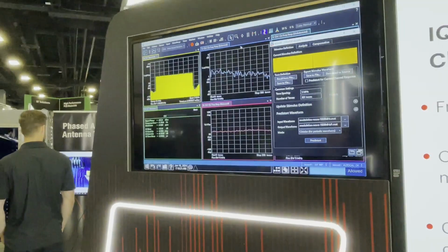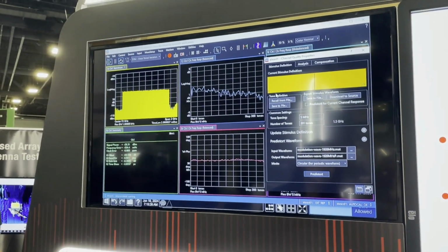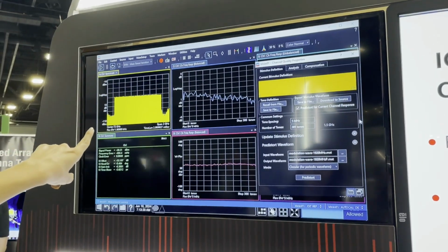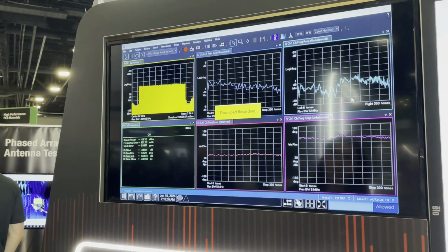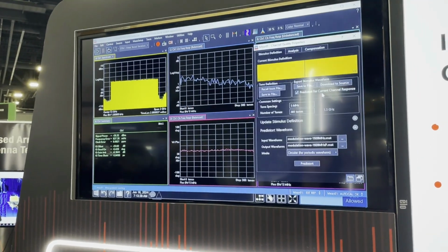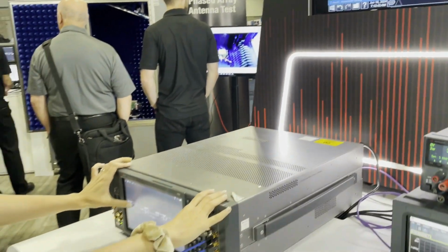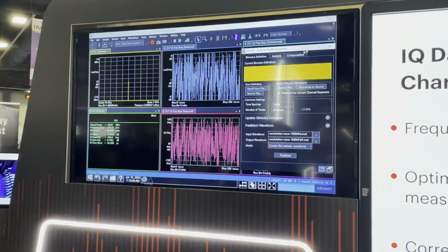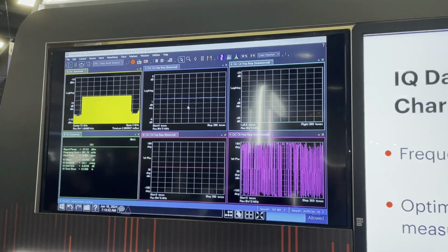Once that's done, I can try and demodulate both of these signals using VSA. What I'm going to do first is pre-distort our calibration comb so that you can see just how good of a job it does in correcting for the IQ imbalances of the system. So what we expect to see here is a decrease in the magnitude of the images in our system.